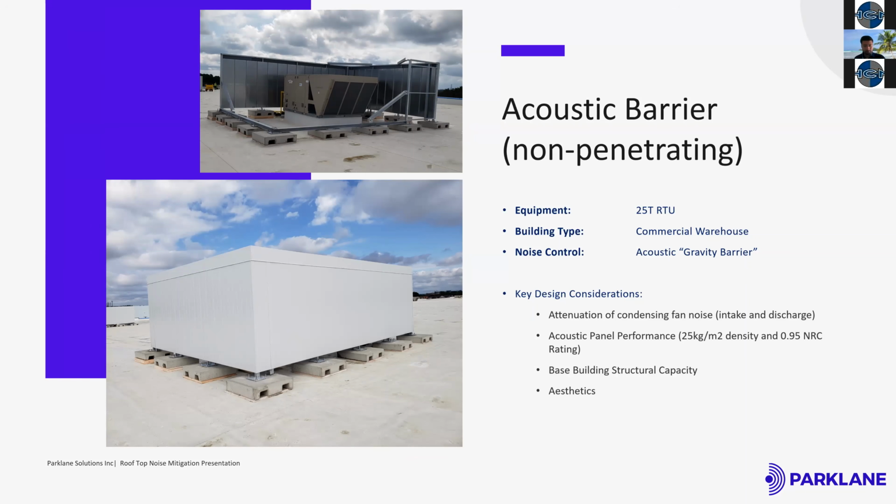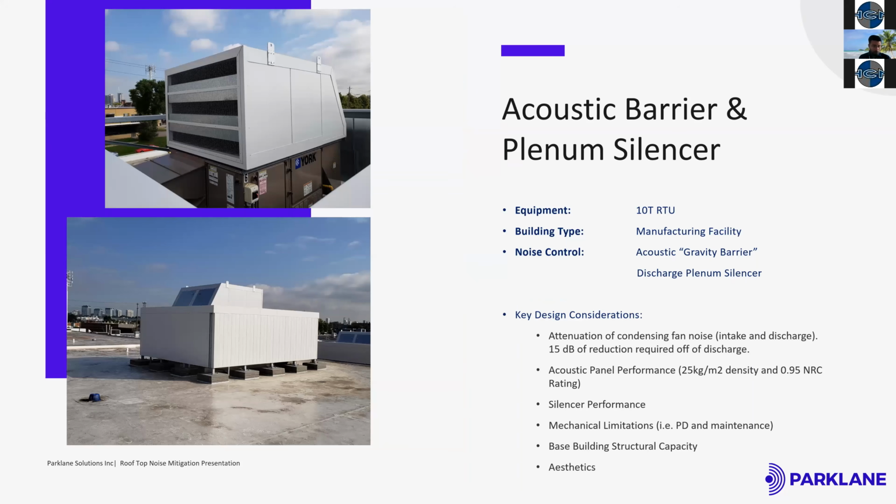Okay. Next question is, for the silencers or other structures that are added, who designs the structure? Who checks to see that the HVAC unit can accommodate the additional structure attached? Right. Typically, we do that. In some instances, the weight of the silencer is so minimal that it wouldn't really impact the unit. Before one goes about designing it, we reach out to the mechanical equipment supplier and make sure that the weight of the silencer can actually be handled by the unit itself.